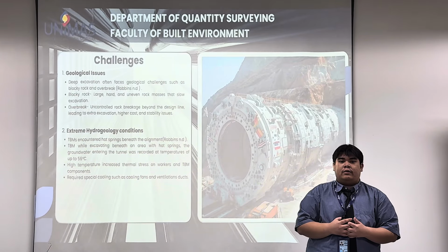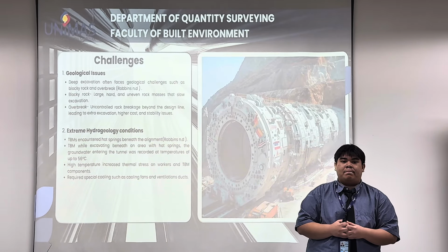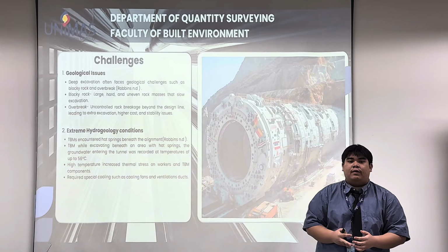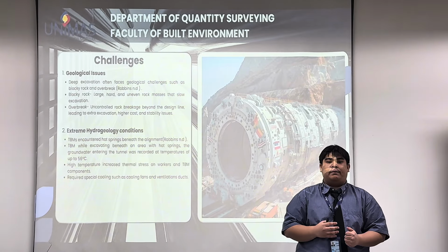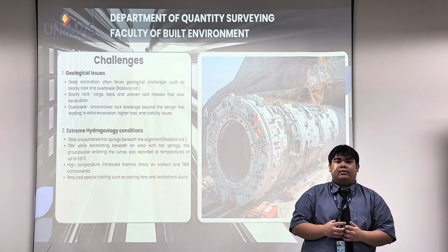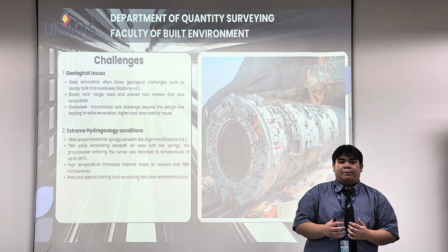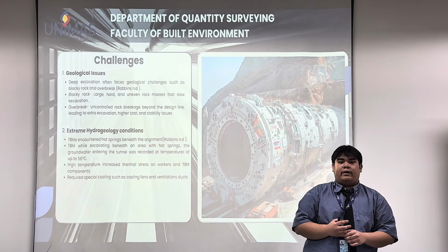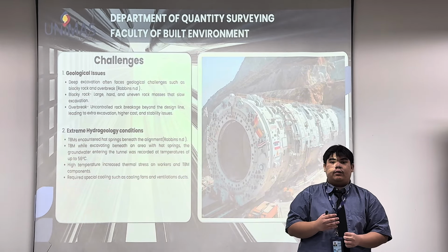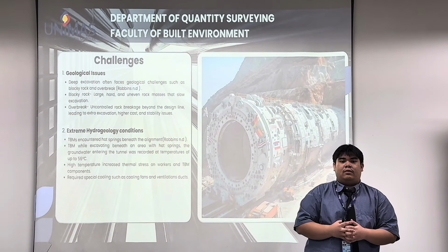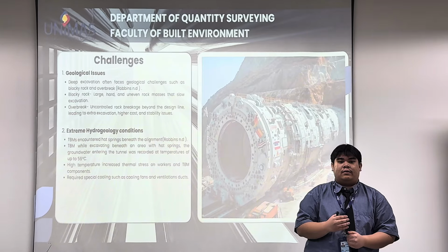The second challenge is extreme hydrogeology condition. The TBM encountered a hot spring beneath the alignment. While excavating beneath an area with a hot spring, the groundwater entering the tunnel was recorded at a temperature of 56 degrees Celsius. High temperature increased thermal stress on workers and TBM components. So this project required special cooling such as cooling fans and ventilation ducts.